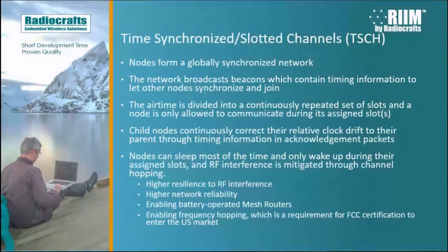So with this, you will have sleepy leaf nodes and even sleepy mesh routers. Another thing is that it makes the network more resilient to RF interference and more reliable, and it enables frequency hopping, which is a requirement for certifications needed to enter the US market.